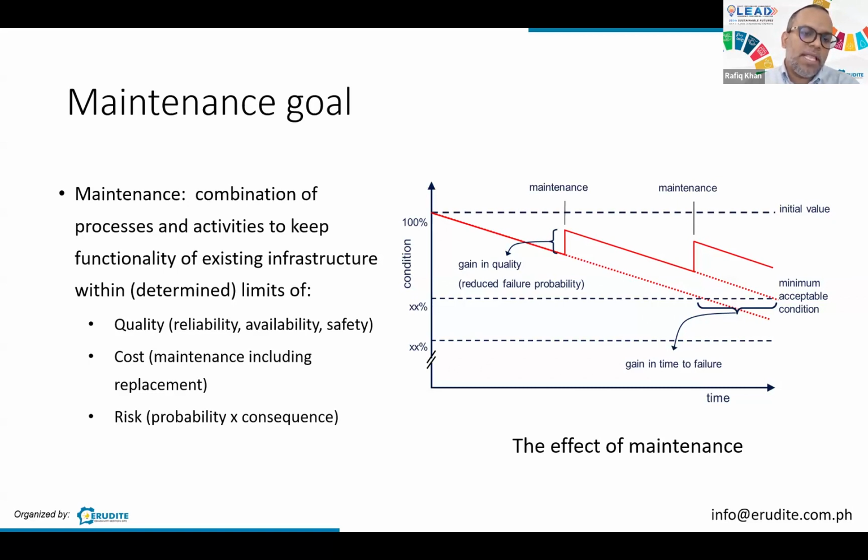Cost: whether or not doing maintenance and replacement work is expensive, because if it's too expensive, maybe just replacing the whole component is cheaper. Over time, spare parts can get quite expensive, and you want to decide whether or not you want to have further replacement. If it's not financially viable, sometimes it's good to have a complete replacement. Risk, again, probability and the consequence. So you always have a function of these three. What is a good balance of these three?